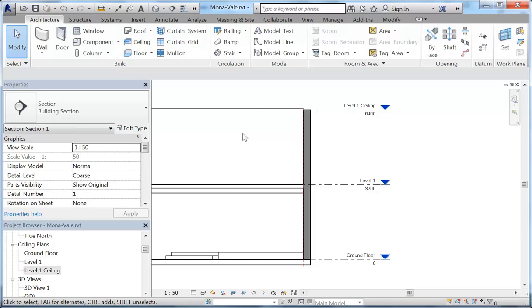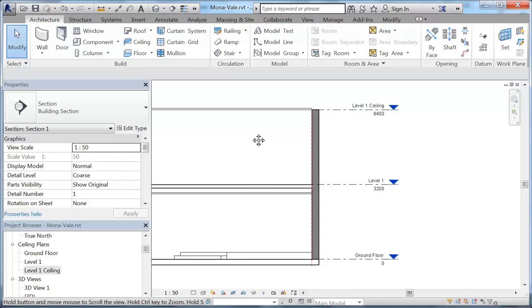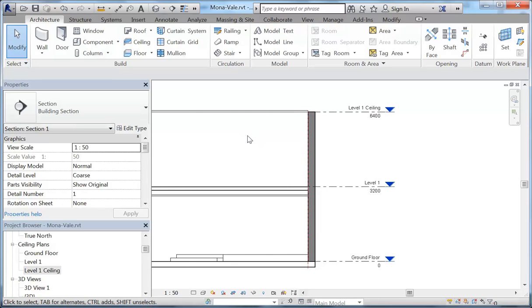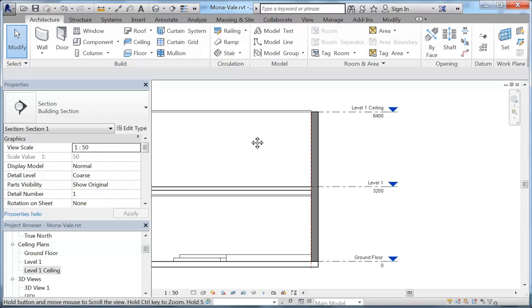So again, just want to be thinking about the design drawings you should be working with. Which reflected ceiling plans would you need in a project like this? The ones where you're going to put lights. Lights, yep. So what would they be called? Just in general. Yeah, not even thinking about Revit, just thinking about what they'd be called. So, yeah, you have ground floor reflected ceiling plan and level 1 reflected ceiling plan. Right? So they're your 2 reflected ceiling plans.